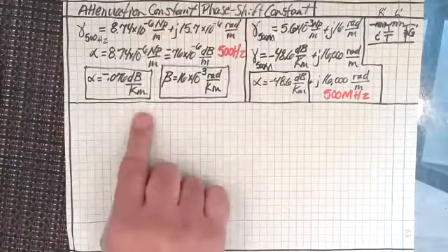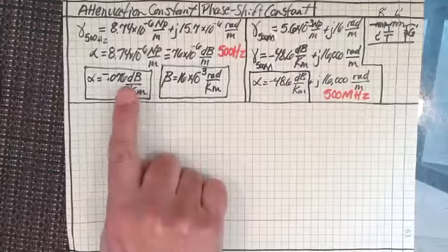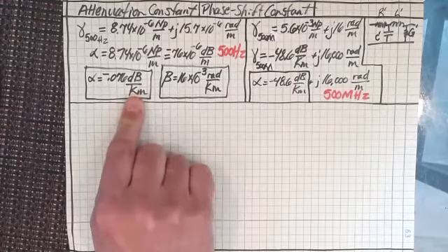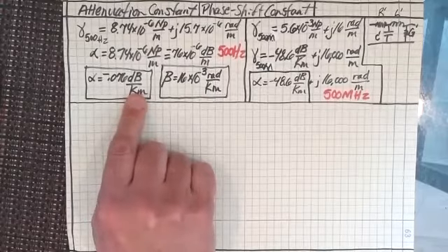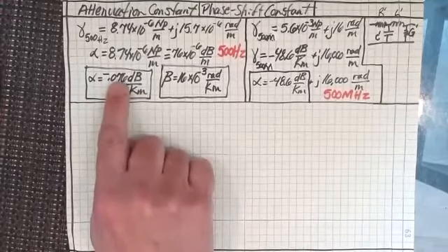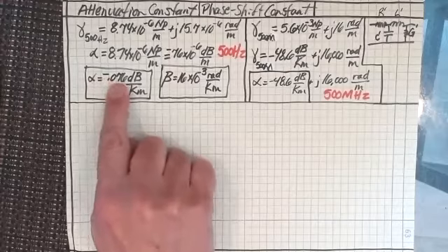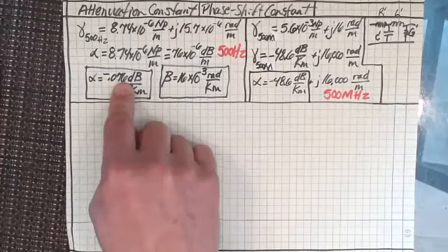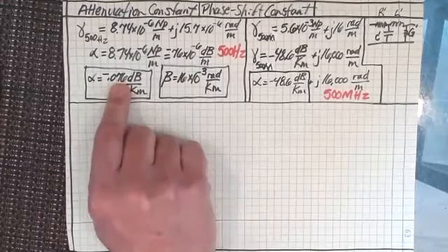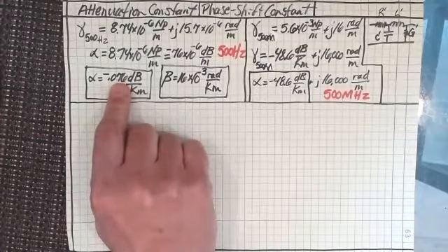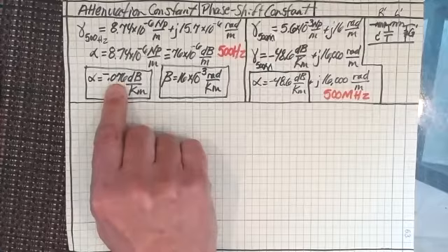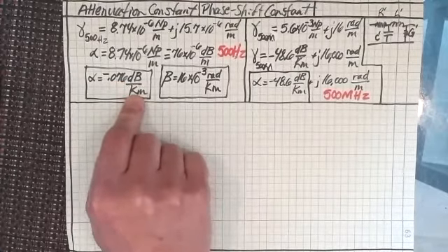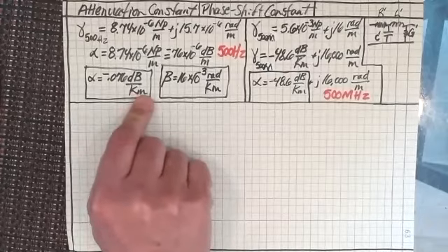Theoretically, if I had a 1,000-kilometer long cable, right? No kinks in it, no connections, just a 1,000-kilometer long cable. That would only come up to minus 76 decibels attenuation, right? That's not hard. You could easily put a detector at the other end that could look at a waveform that came in at, let's say, 1 volt peak to peak, and then had 76 decibel attenuation at the other end of it, and that would be 1,000 kilometers, right?